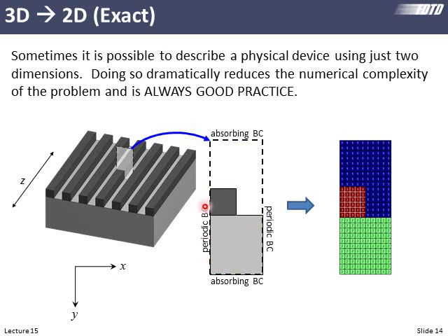We put a periodic boundary condition on the left and right. That makes this look infinitely periodic left and right. We'll have our absorbing PML boundary condition at the top and the bottom to absorb outgoing waves. So you can imagine taking a total field scattered field source, a one-way wave, and launching it into this device and watching it bend and wrap and resonate and do other things. And so we would populate our 2D grid in terms of the permittivity, putting 1s up here for air, 3s down here for the teeth, and then 2s down here for the substrate.